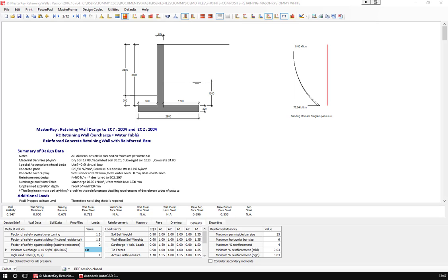Is crack depth considered? Yes, it most definitely is. I mean, cracking of the soil is, to me, the most scary thing. People think that they drain everything, but if you shrink back and it freezes or anything, and you cause a gap here, certainly you're going to get water up that 1 millimeter. And put a pressure on it.